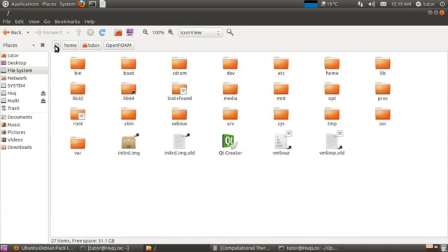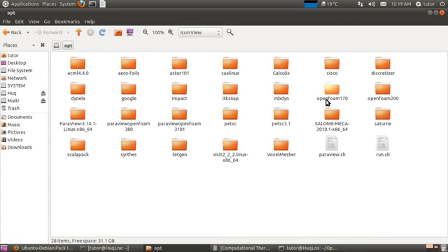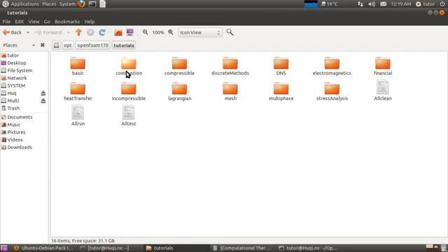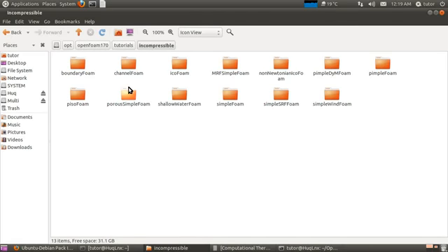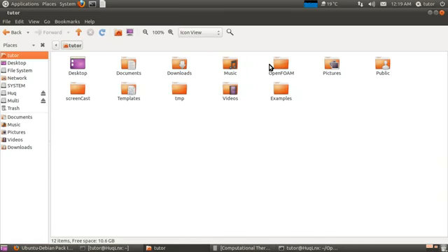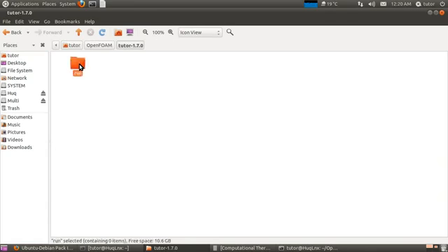So first I go to my, typically this is where it is installed, in this directory OpenFOAM 170, tutorials. We are going to do an incompressible case and icoFoam, and so in this I'm going to copy this example cavity. So I copied this cavity and I go back into my run directory and paste it here. So now what is inside this, Shoaib will tell us. Thank you, Sadiq.